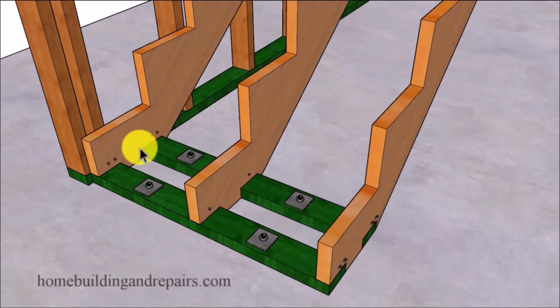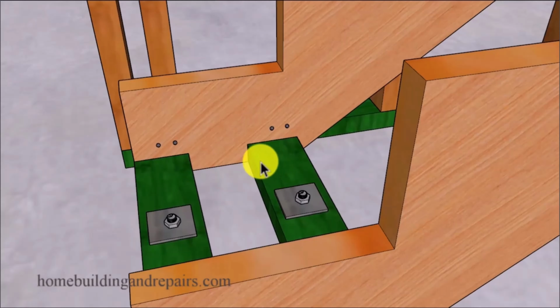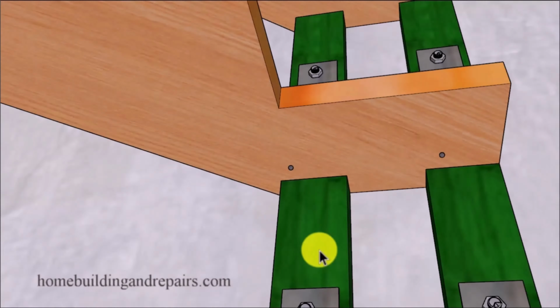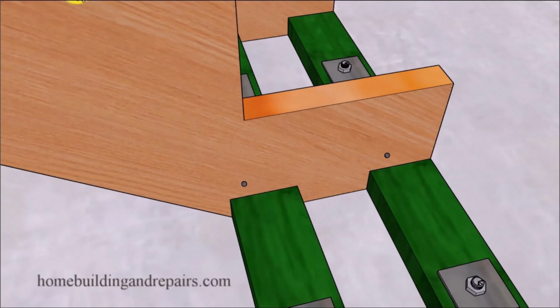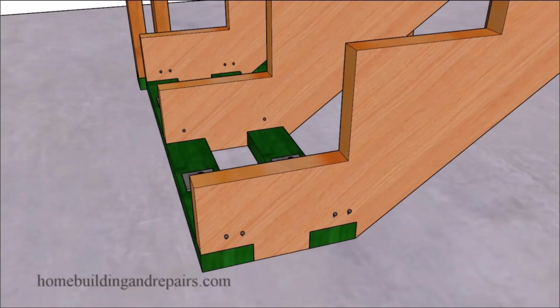So what about this design here? Is this something that might work better for you? You're going to get both of the framing plates, which is what I would like to see, plus a couple of notches that in your mind might prevent the stairs from sliding forward, even though these notches wouldn't be necessary if the stringers are securely fastened to the base framing plate. So something like this would make me happy and make those of you happy who believe that this notch right here is somehow going to work better than the very first example I provided in the video.